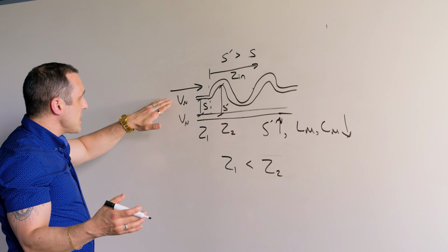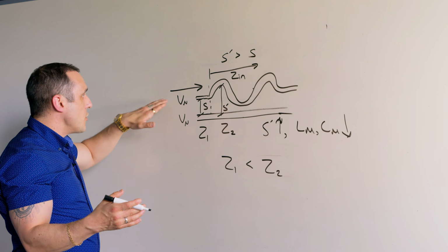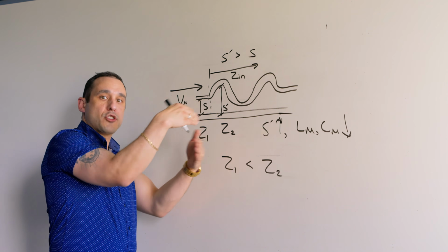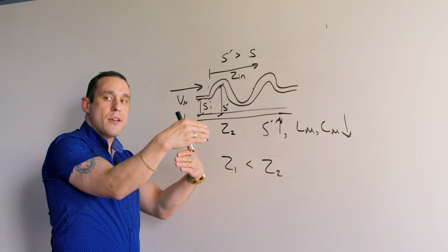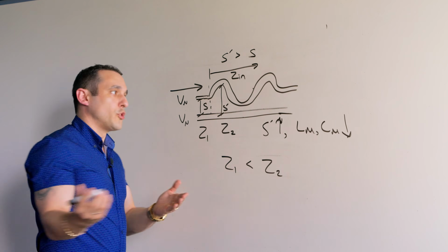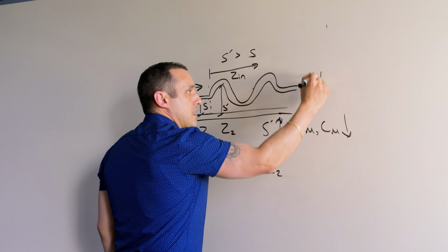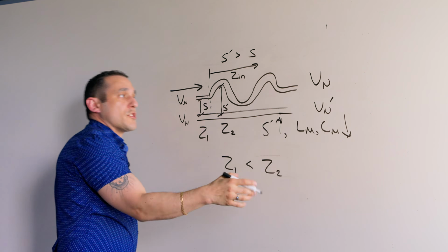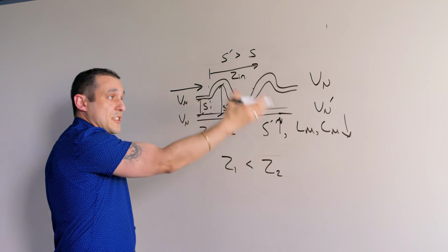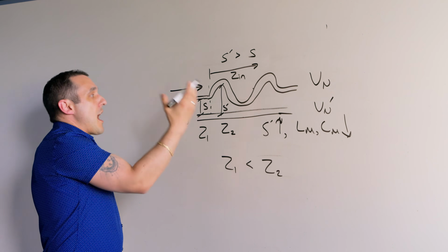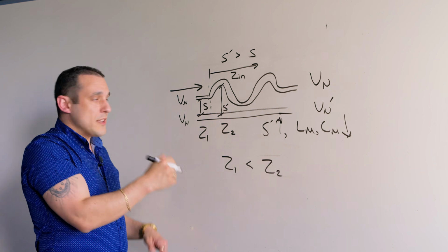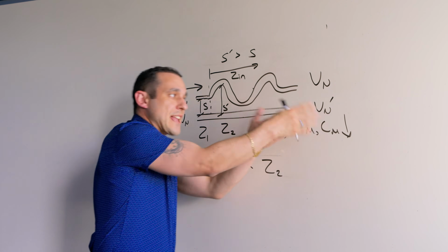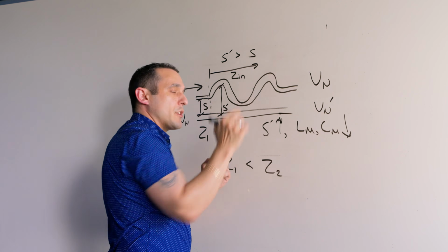Well, here, this equal polarity noise on both traces now becomes unmatched or unsynchronized in time. So now I get differential noise that exits here. So I basically get some Vn and then some Vn prime. So now I have differential noise that exists between these two traces. Ideally, if we have common mode noise that enters a length tuning section or is on a differential pair, we want it to stay as common mode noise at the output of the differential pair.